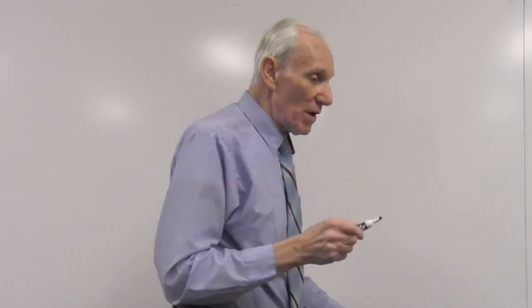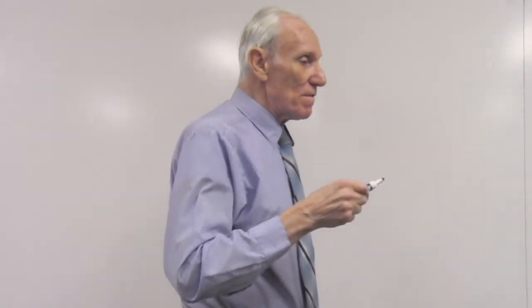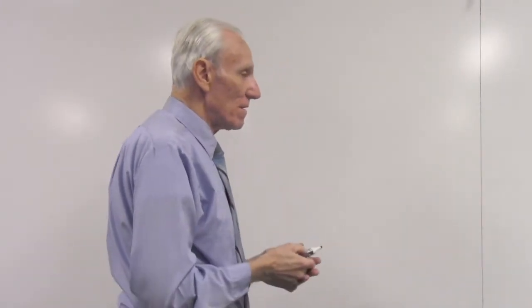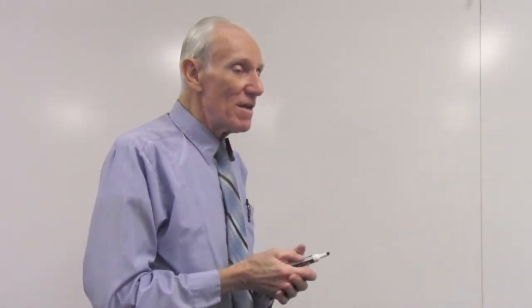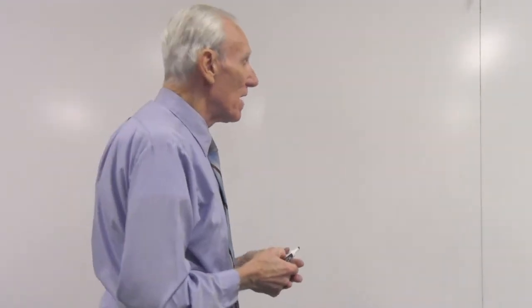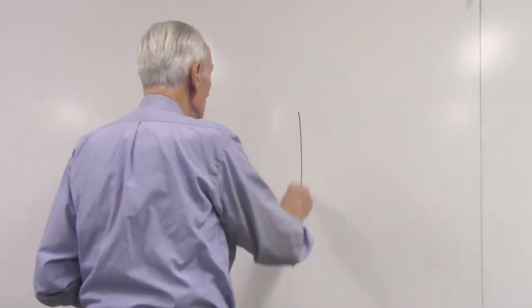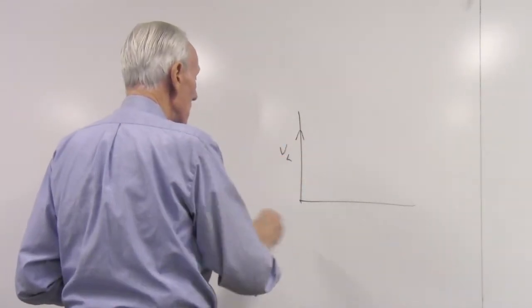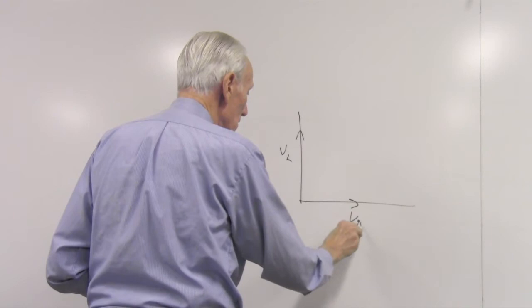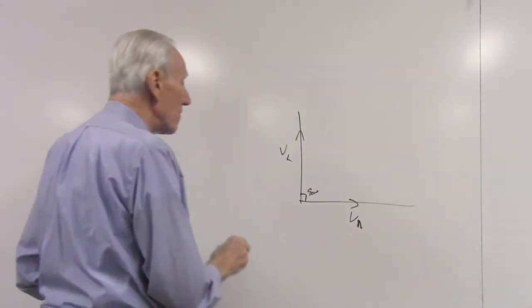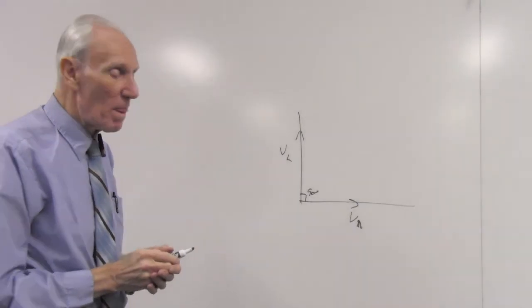If you haven't, we'll have to defer the deep discussion of what's going on here to that time. But the point here in the lab is that there is a phase change when you have an inductor. If you have a pure inductor, the phase change turns out to be, go through the mathematics in the handout, 90 degrees. So the voltage across an inductor compared to the voltage across a resistor in a series circuit is 90 degrees for a pure inductor.